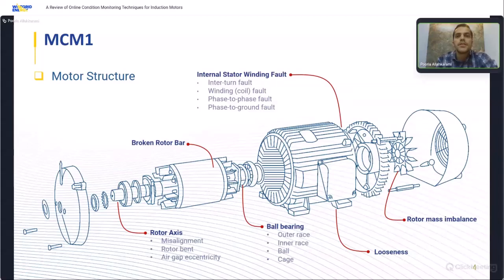These laminations prevent eddy current flow in the stator, and we place them together to make the stator core. Then we have the stator windings or coils, which have copper conductors, and the stator frame. Now, for a winding or coil, we need the slot insulation, the coil windings, and the phase separation in the windings.